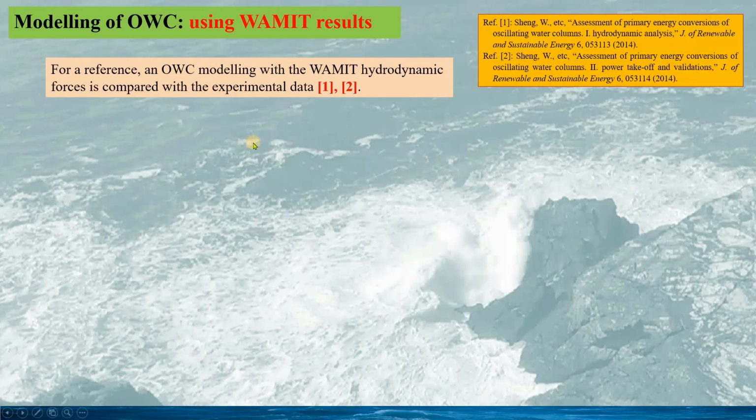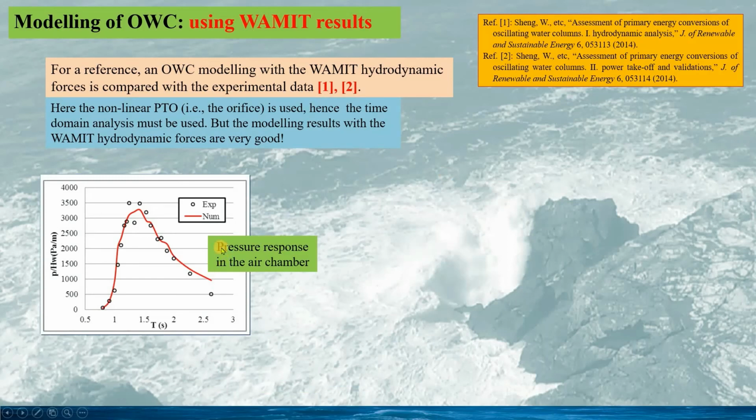Therefore, the numerical modeling based on the WAMIT hydrodynamic parameters is in the time domain, since the dynamic equation is not fully linear anymore. If we compare the numerical modeling with the experiment data, this is the pressure response, and we can see the experiment result and the modeling are very close.